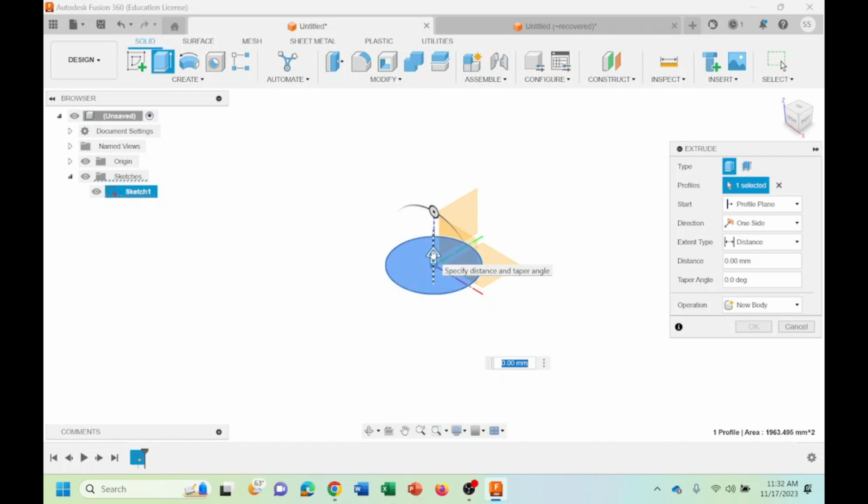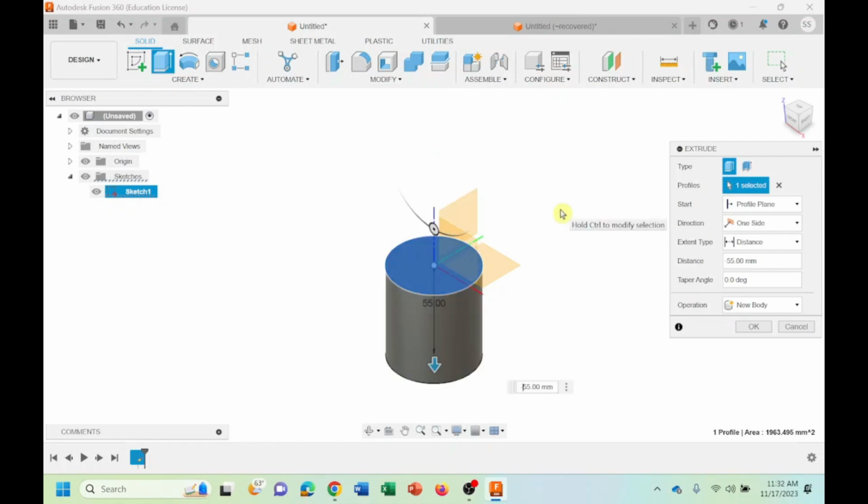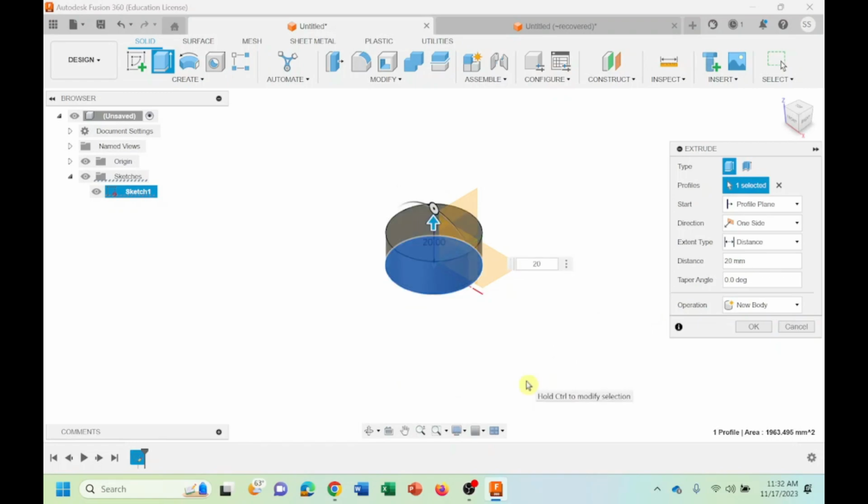As you could see, even here, you could extrude that in any direction that you want. Now I'm putting that in the positive. You could do the same thing if you just add a negative number, it goes to the opposite direction. But be careful, don't extrude under the negative Z because your 3D printer plate is the Z. You really couldn't go to the negative, right? Just be careful whenever you use that. So you could do different extrudes based on your need.